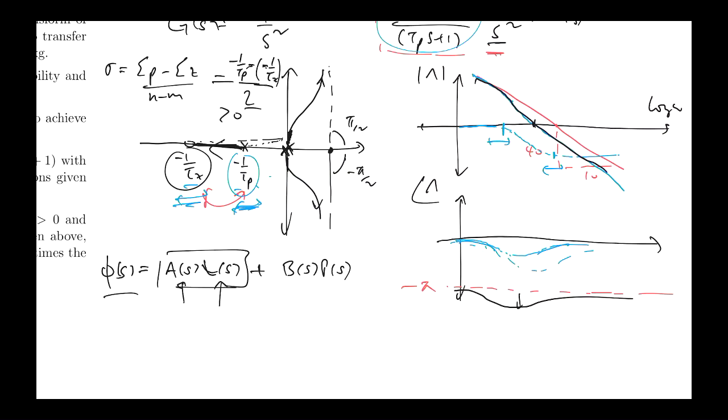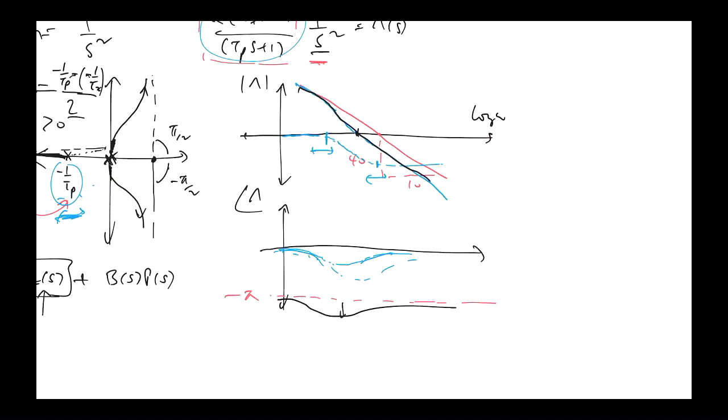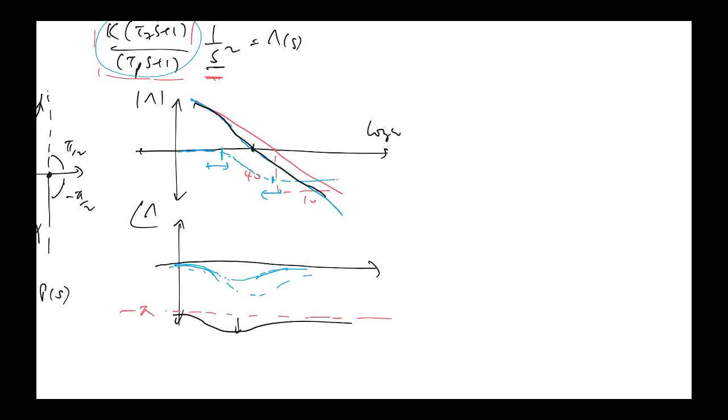And if you think about what the Nyquist plot might look like, the Nyquist plot is just a polar plot of this, really, right? And you'll see that by virtue of the phase always going beyond minus 180, you'll start off here at very low frequencies, but as you increase frequencies, you'll move into this quadrant, because this is minus 90, minus 180, so this is less than minus 180. This is like going below. You're going to end up in this quadrant, all right?